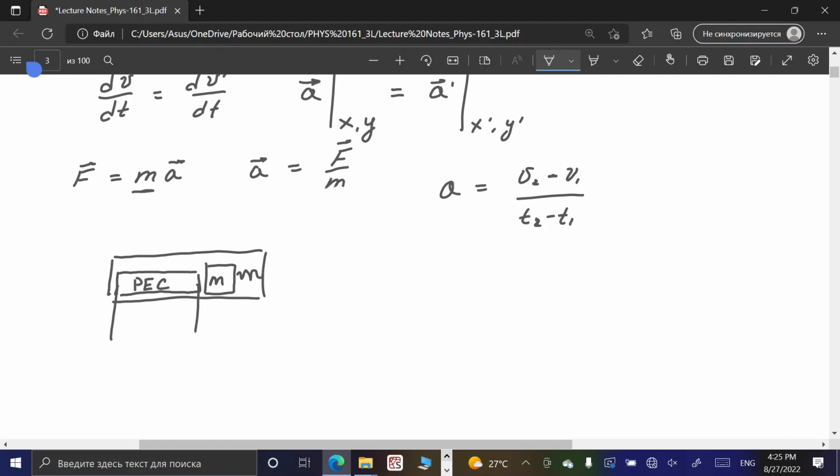So we can measure with a voltmeter the potential difference at the edges of this piezoelectric crystal as a function of force which compresses it or stretches it. So it can change polarity, depending on compression or stretching. So if we have such a crystal calibrated, what does calibrated mean? That we have this dependence of force exerted on this crystal versus bias,